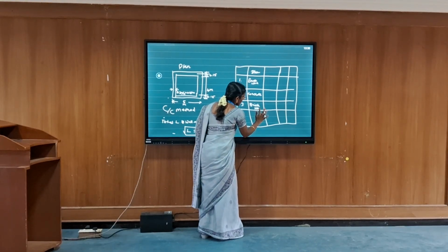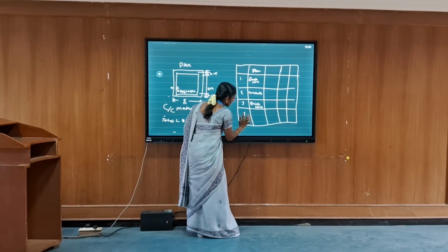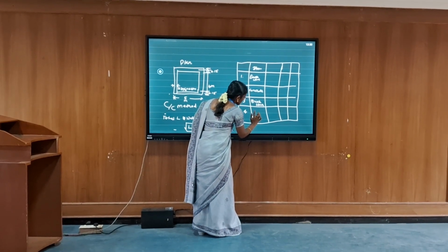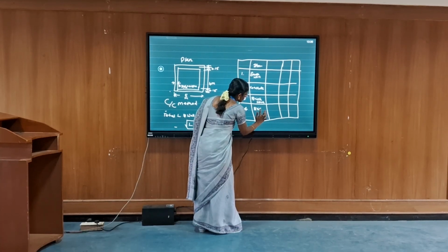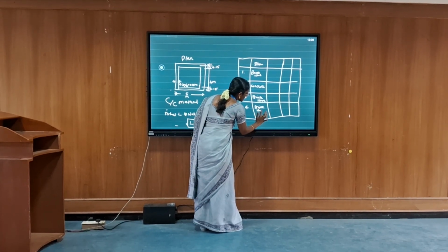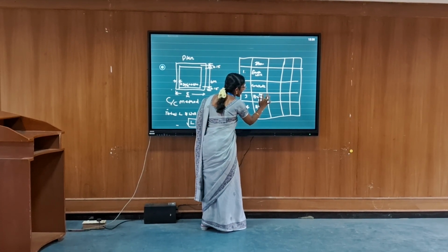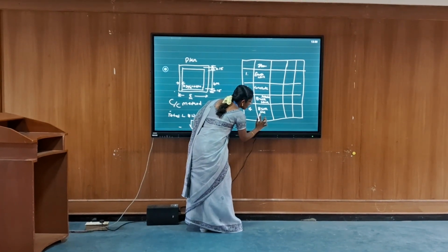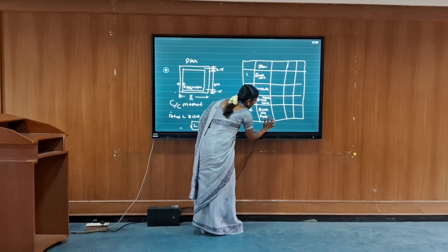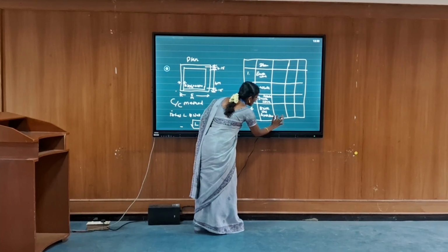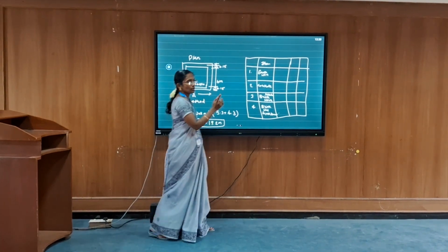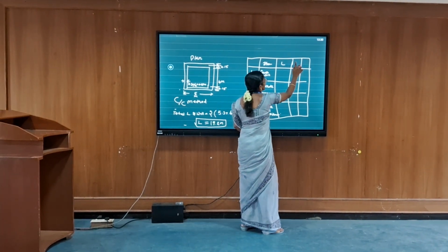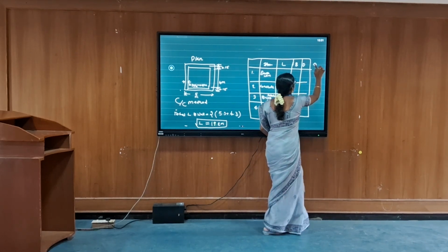The next, and the last one, is the brickwork in superstructure. So you have to calculate both things. Brickwork in foundation you have to calculate first. Next, brickwork in superstructure you have to calculate. For calculating this, there are length, breadth, depth, and the quantity.